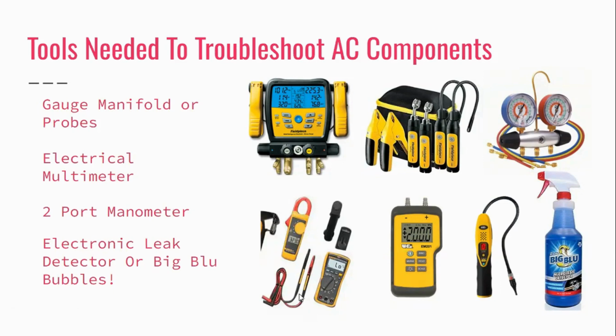So gauge manifold or probes. Electrical multimeter. Right here, we have a Fluke one, just because I put a Fluke one on there. I do use a Fluke 87, and I use a Fieldpiece as well. But it doesn't matter, again, as long as it has an amp clamp. There are a lot of meters out there that do not do amps, so make sure that you have this clamp on the end of your meter before you buy it. And then a 2-port manometer. There are 1-port manometers. The reason I say 2-port is because if you're checking gas valve pressures, you need to have a 2-port manometer. Manometers can check gas valve pressures, but they can also check airflow pressures. So you definitely want one of those.